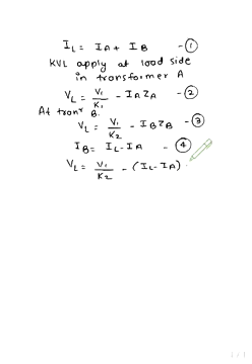From equation 1 we can find the value of IB, and put it in equation 3. We know IB is equal to IL minus IA. So putting this IB value in equation 3, we find VL is equal to V1 by K2 minus (IL minus IA) into ZB.